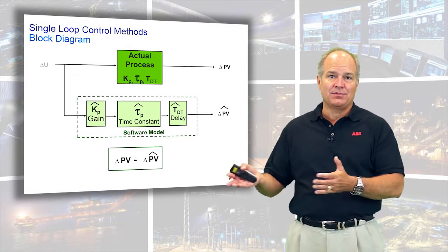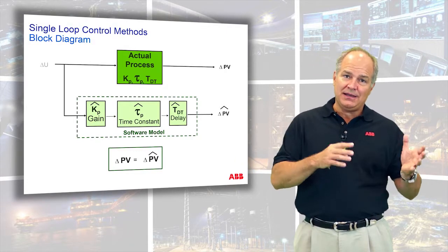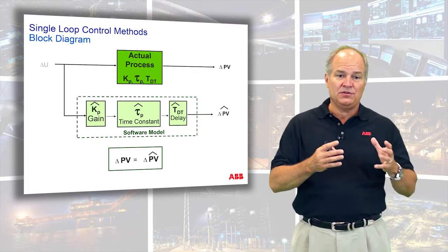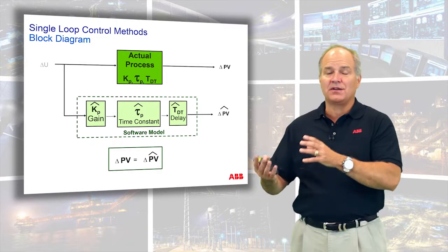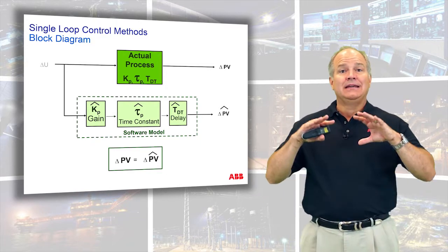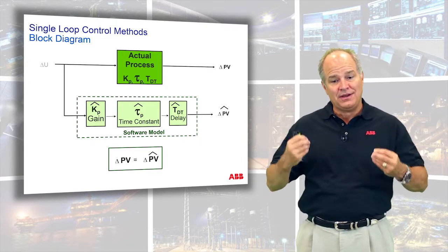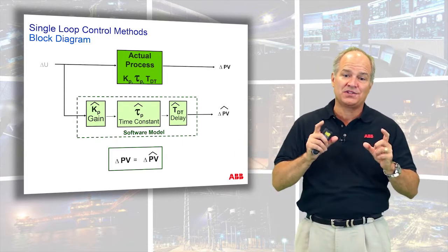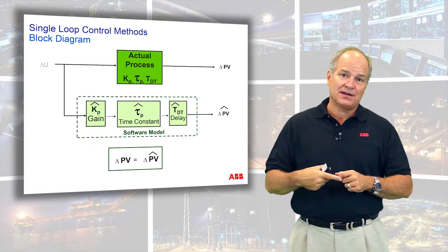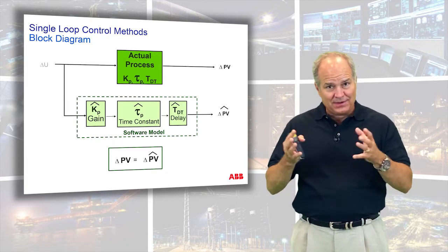I call them setup parameters. In the traditional PI algorithm, you use the process model to calculate your controller gains. In a dead time compensator, you actually have to enter those model parameters into the software, because we are simulating the actual process. That's what's happening under the hood.